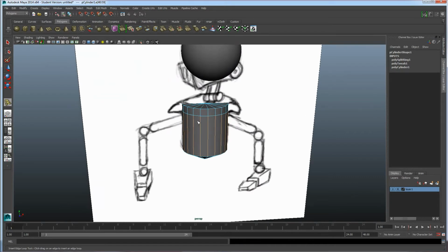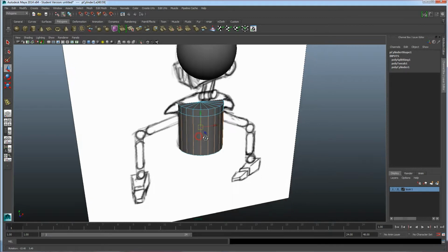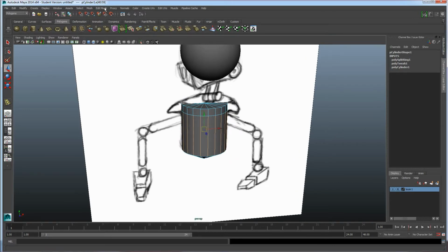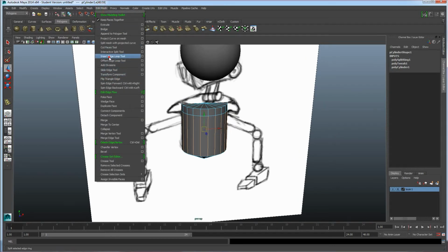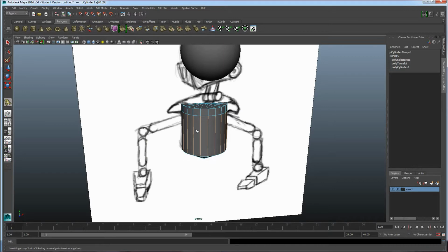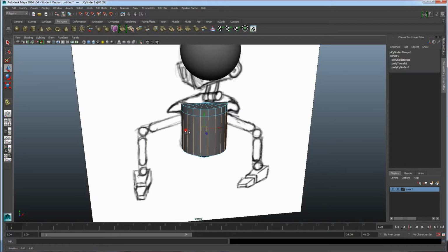Alright, so to cancel the move, notice how the arrow cursor looks a little bit different. You can press, let's say, W, which will switch out to your move icon, which cancels the current command you have selected. Or I guess you could probably also press Enter to cancel it. So Edit Mesh, Insert Edge Loop, press Enter. Nope, we'll just use W to cancel.